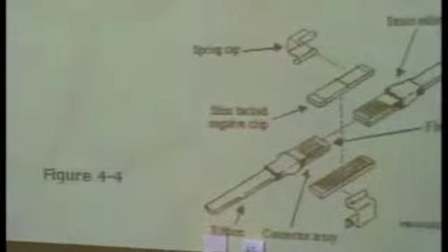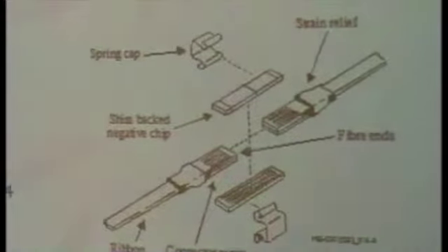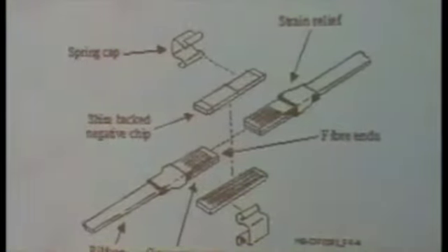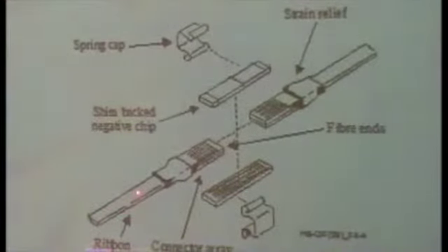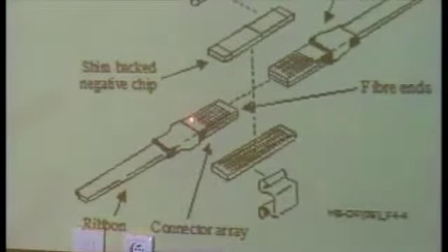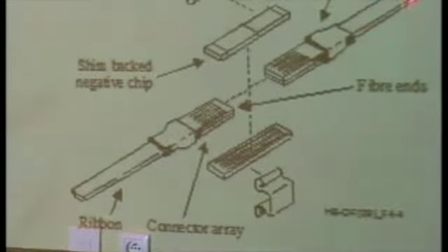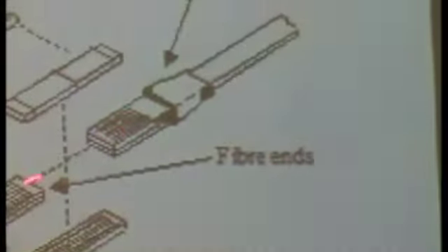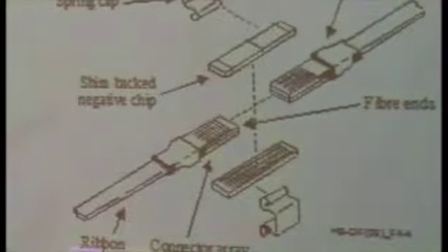Then there is a lot of fibers here, and the ribbon is a set of 4, 8 or more fibers put together, and this is like a flat cable, very small, and it's possible to put this ribbon cable inside a part of a mechanical splice, other ribbon cable on the other side, and have some mechanical device to put together and keep, after adjusting the extremity of both in a good alignment.